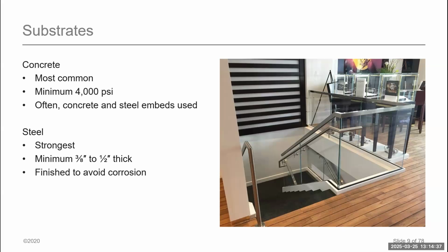The other thing we need to take into consideration about the concrete is its overall strength. The strength of 4,000 PSI is a standard. That's what I just talked about from an embed standpoint. But if you start getting stronger PSI concrete, 5,000, 6,000, which we'll typically see in larger commercial buildings, as we move up to high rises, we can see values that get up to 10,000, 12,000 PSI. That will reduce your overall embed required for your anchor and could also possibly reduce your required edge distance.